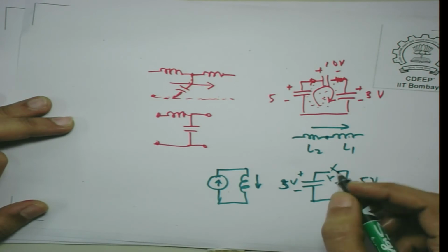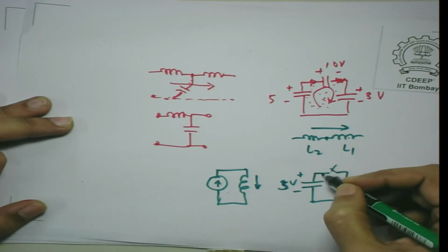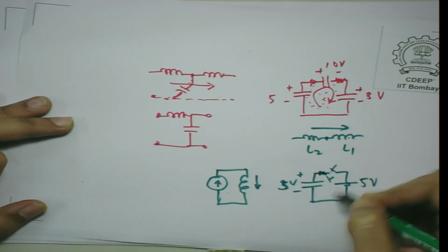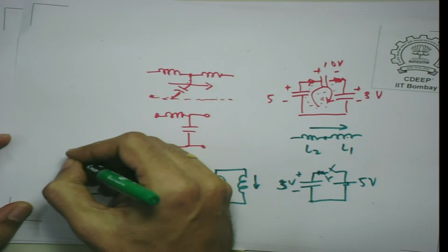In real life, as I mentioned, the parasitics save us from having infinities, because there are resistances here and the loop inductance is here. So, you will not have KVL violated in real life, but you will still have an extremely high current, because these inductances and resistances, or the parasitics, are extremely small. So, remember that the choice of what you connect across a device has to be done carefully. In case we have situations where you may have problems, for example, you are having an inductive current flowing in a circuit and you want to interrupt it.